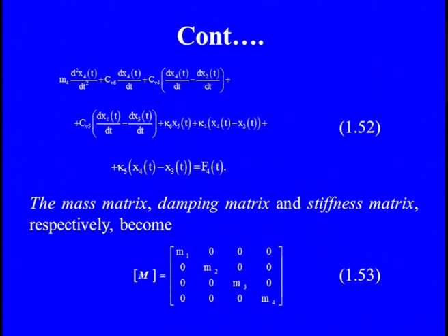Now, if we look at how the mass matrices are arranged along with the masses placed in the equations, you can see that the mass matrix is again the same, M1 to M4, since there are 4 masses. Since it is a 4 degree of freedom system, the mass matrix is again diagonal, symmetric along the diagonal.